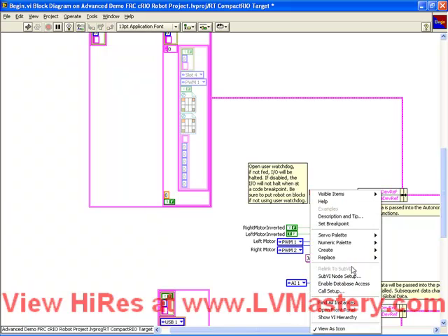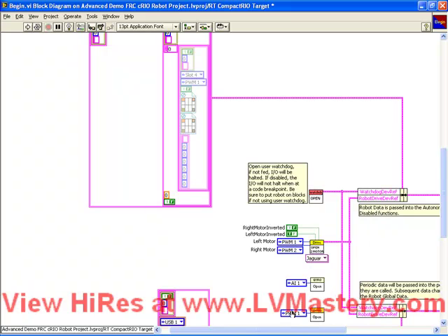We'll wire up the channel, which again is PWM9. So we've used these functions now to open up device references to the gyro and the servo. So if you remember from the basic robotics framework, we had to wire these device references into the main code so that we could use them for the gyro get and the servo set angle. And if you remember even further into the autonomous mode modifications for the basic, we had to put that data type into the robot global. By putting it into the robot global, we then made those device references available for the autonomous independent VI.